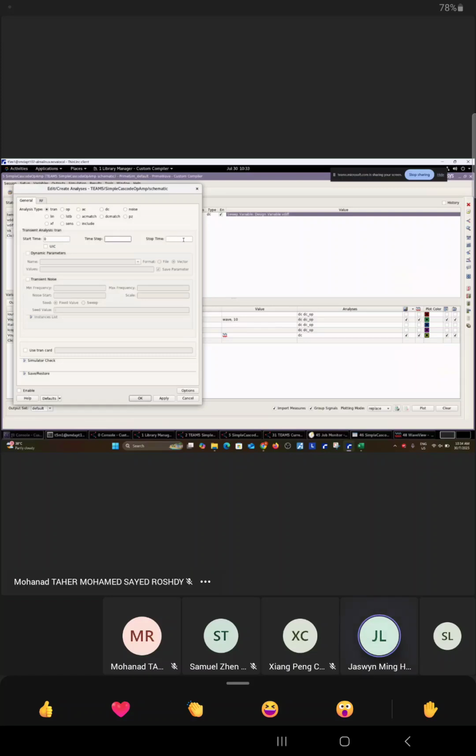Okay, maybe 300 hertz. So one period is about 1/300, which should be 0.33 milli, something like that. Yeah, 0.003, so 3.33 milli, right? So maybe you put one step to be 0.0005. Then the stop time maybe we put at 0.005.